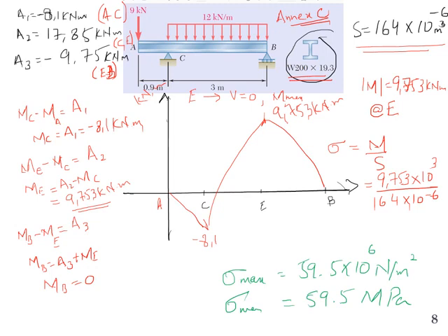When you have loading like that shown in this example, it is easy to calculate, but for complex loads it becomes difficult. In my opinion you should learn both methods, but for me, the previous method, where we used sum of forces equal to 0 and sum of moments equal to 0, the equilibrium condition method, is easier for finding the shear force and bending moment.